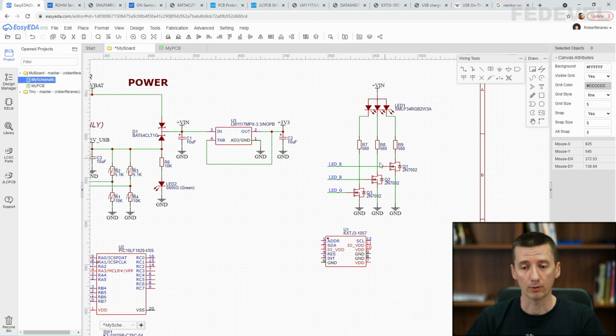And when you use these transistors, you can power these devices or components from all kinds of different power sources, and you don't really need to think about whether this power is going to influence your microcontroller or not. So this connection is much safer, and I use it a lot to control anything through the pins of the microcontroller. I almost always use these transistors, even when I drive LEDs.